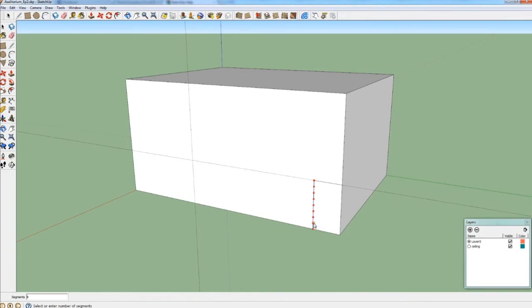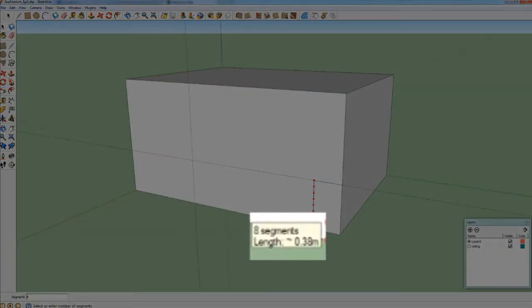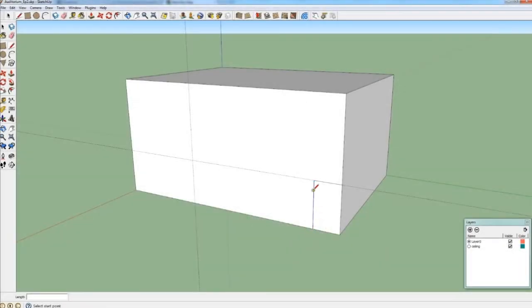You can see also the pop-up message saying what is the length of each segment when you just hold your pointer on this, and then we just move it until we find 0.15 meters, which is 20 segments. So I need 20 segments, 20 stair treads to be fitted here.